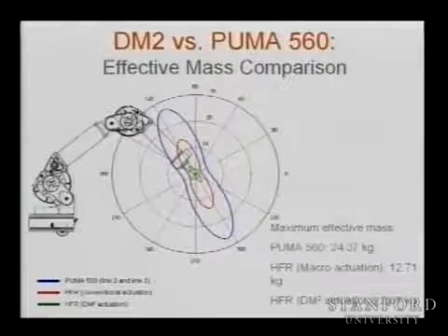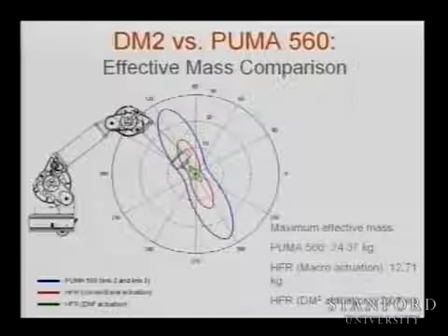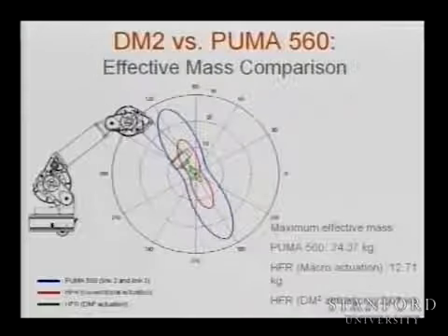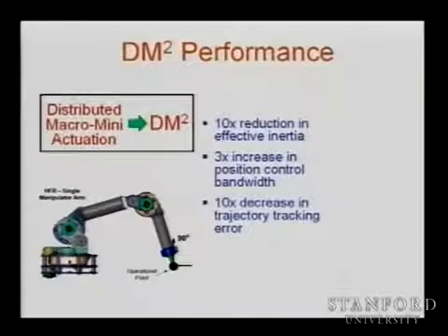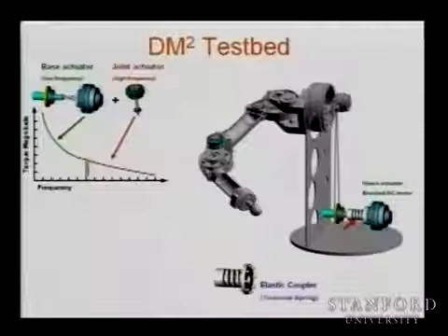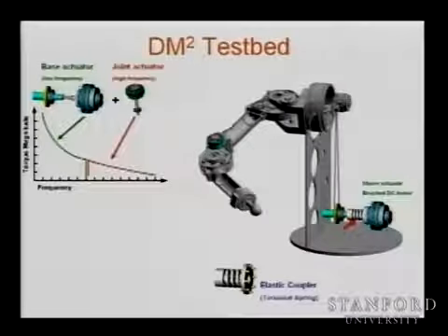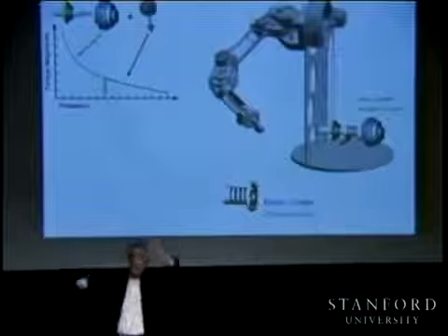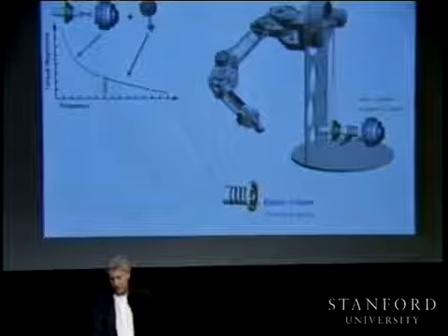So you understand those inertial property. The green one is what you have now. You reduce your effective inertia by 10 times, and immediately you improve your control performance. So this concept is quite complicated because it requires this elasticity, requires the big motor, requires transmissions to couple it.